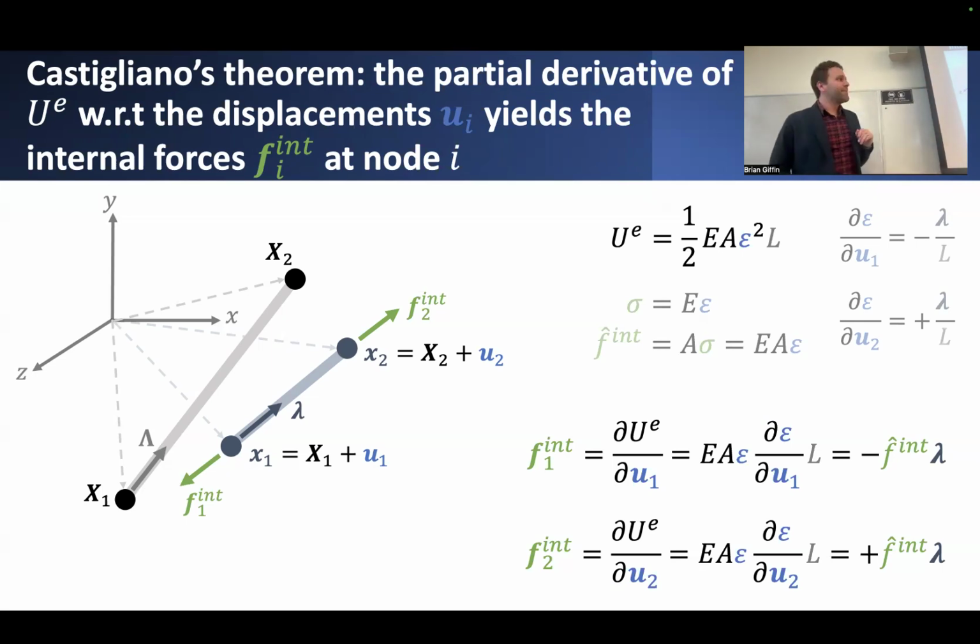Well, when we take its derivative, we can recognize that a few things are staying constant. We can assume, at least for the time being, that maybe the material properties, the cross-sectional properties, and the overall length, the initial length that is, are relatively constant. So let's just keep them constant. So if we take derivatives of this expression, those quantities will stay the same. But when we take derivatives of this strain-like quantity, in particular, it's epsilon squared. What's the derivative of epsilon squared with respect to these displacements at the ends of this member? Maybe that's a little less straightforward in terms of how we do it.